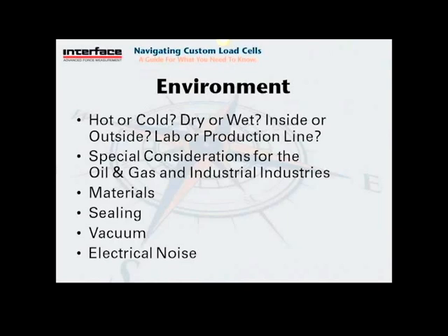We also have questions about vacuum applications, and these have additional considerations depending on how high or how strong the vacuum is and whether outgassing of materials needs to be minimized. Last on the environment is electrical noise that may be coming from electric motors, arc welders, maybe linear actuators that are in the area. And these need to be considered as well to avoid degrading the load cell signal.